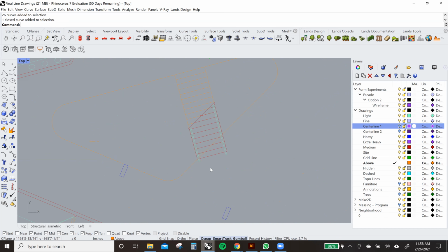This is an example of some of the things that we talked about in class yesterday. So having a break line for the stair there, and you continue the tread of the stair up, and beyond the break line, they take on the dashed lines.